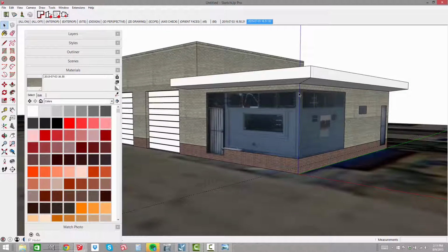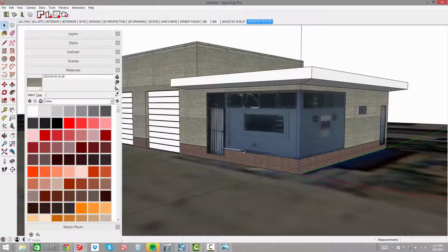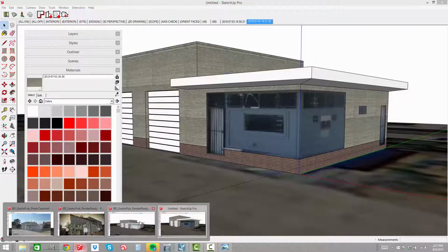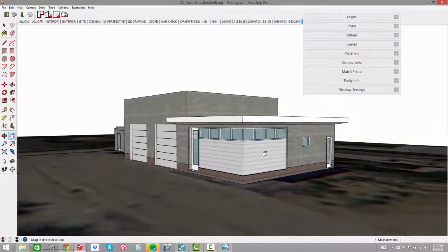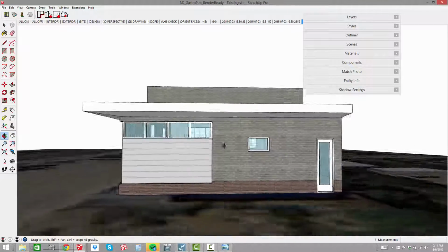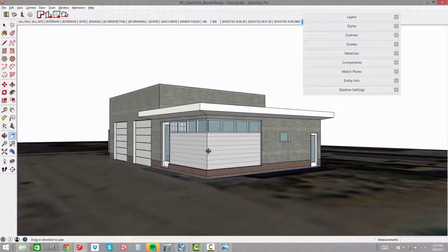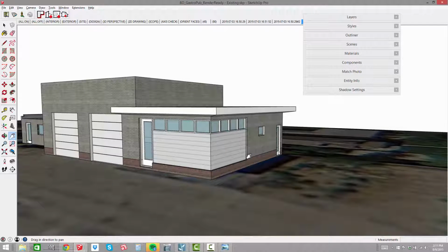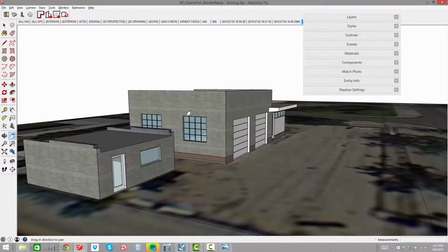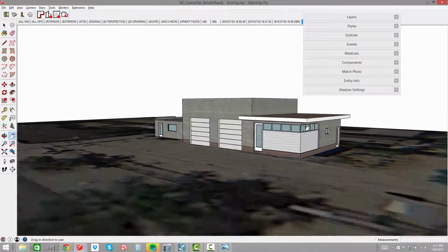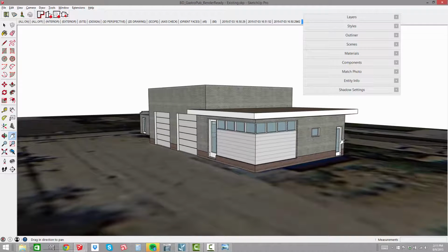You'd continue on and add detail here, and let's see, I think I've got this RenderReady model open, so you can see I've added the texture to it, really went through and fixed everything. So don't think that you guys need to see every single step, but I would suggest you take a shot at definitely doing the doors and windows, and then work around it and just practice using those simple SketchUp tools to push and pull and give this thing depth and get it ready for rendering.